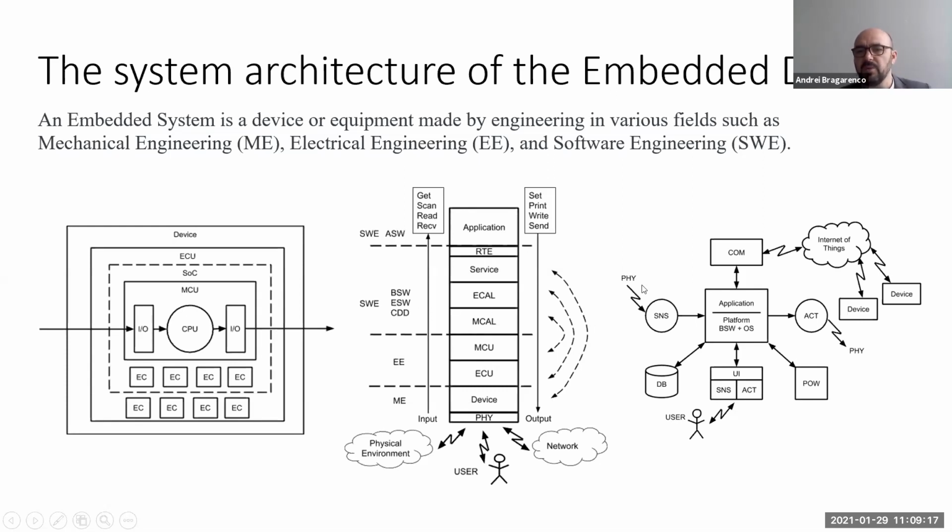In this case, when we are developing those components, we will have some layers, some abstraction, because the right organization of the software will provide us with more flexibility. That means for the microcontroller, we can have a driver, an MCU abstraction layer. And in our case, we have Arduino.h. This is a hardware abstraction layer.